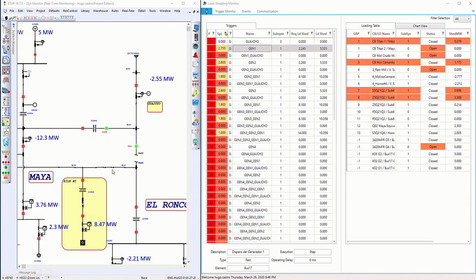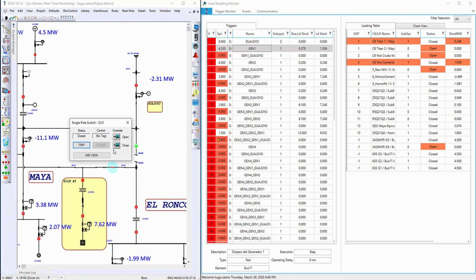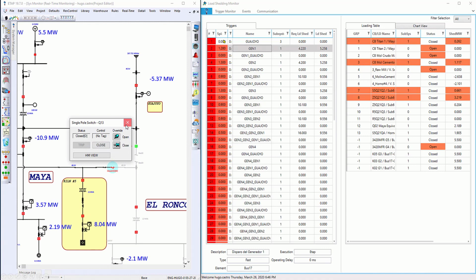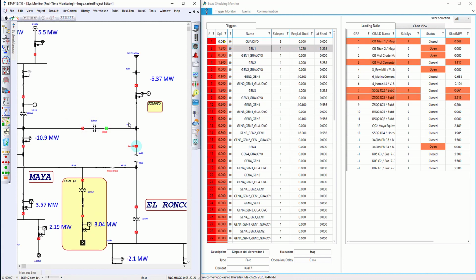in the system. And as you can see, we're doing this for every single possible contingency in the system in parallel on a continuous basis. And this is done in anticipation of the event. Therefore, this makes ETAP ILS a proactive load shedding system that's contingency based and uses dynamics to essentially determine the load shed tables.